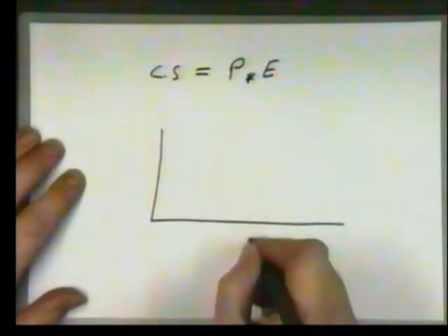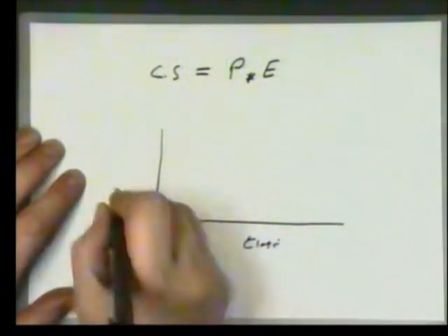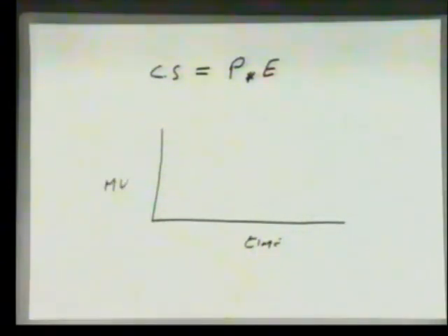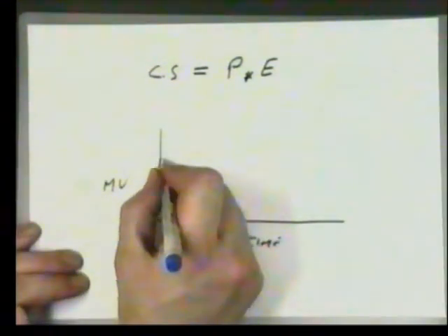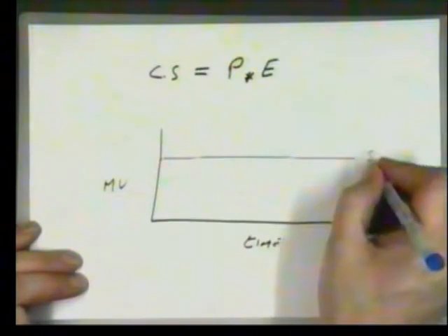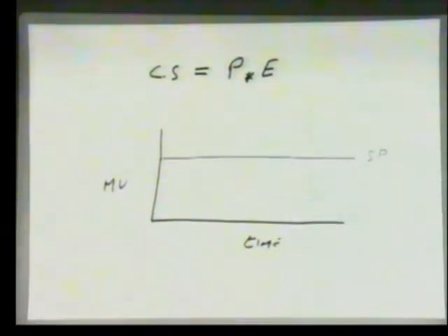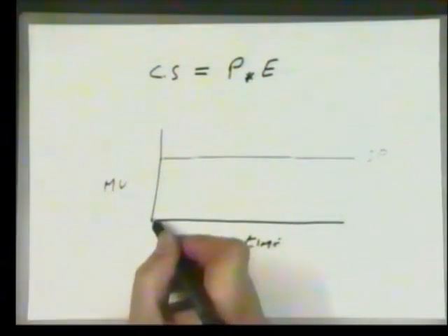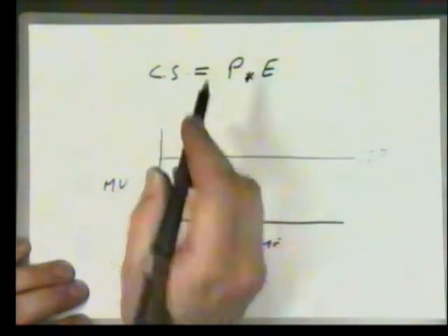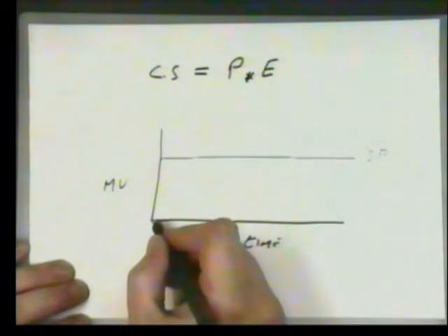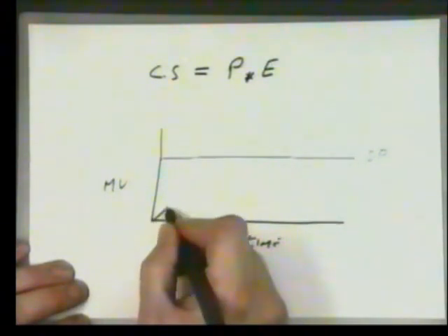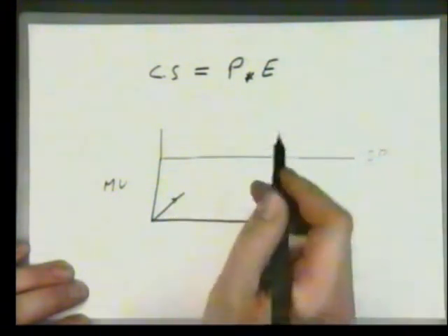Let's look at what happens in real time. In the ideal structure, here again, that's time. This is measured variable. And if we draw in our set point, while we have a very large error, our control system will be fully on. It's virtually like an on-off controller at this point, and it's rising up very rapidly, trying to get us there.